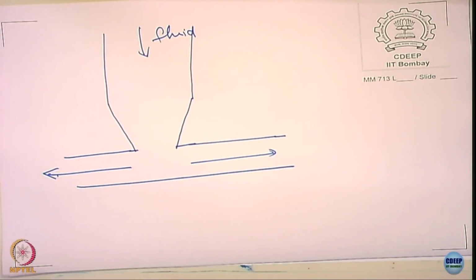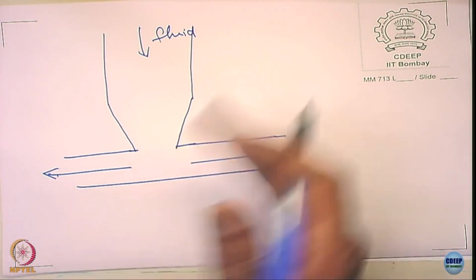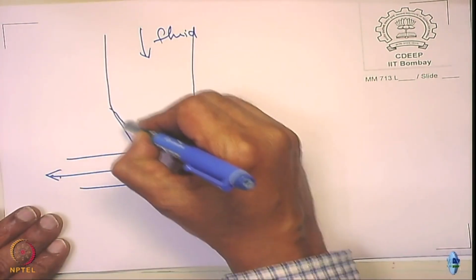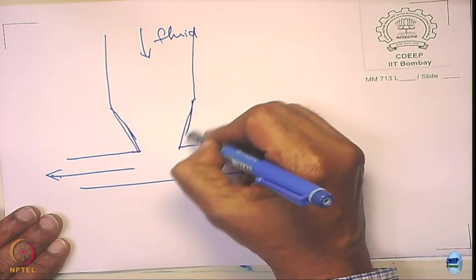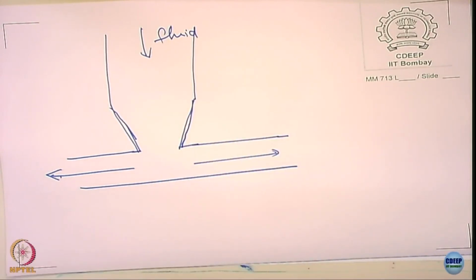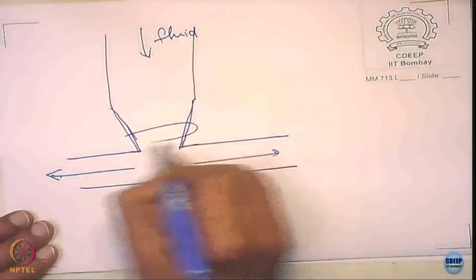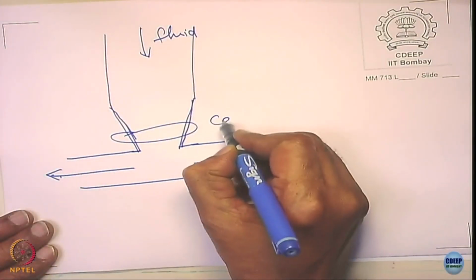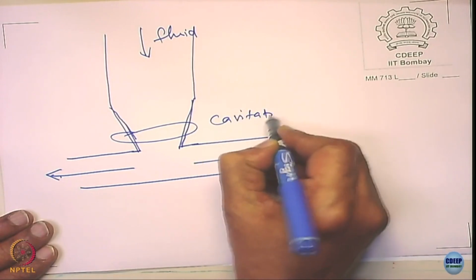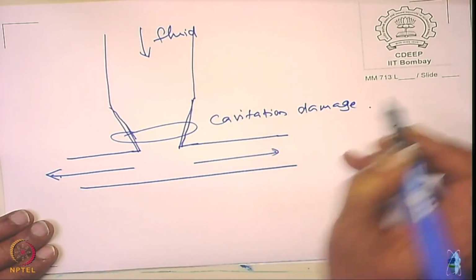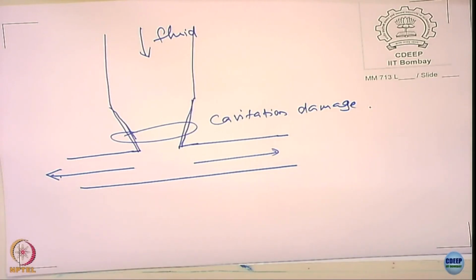Now look at this design here, it is a pipe with a larger diameter and a smaller diameter, and you weld it like this. Where do you think the cavitation damage will occur? Yeah, just at the reduction area, this is the reduction area, right? Because the pressure is increasing.